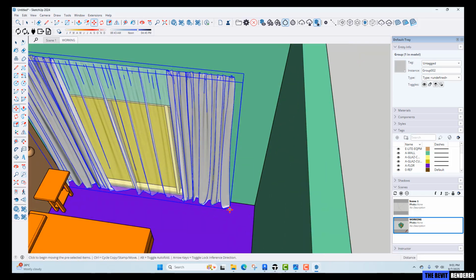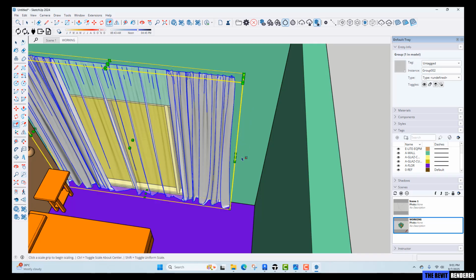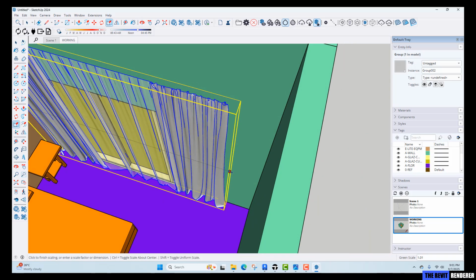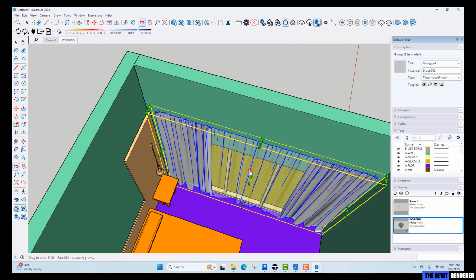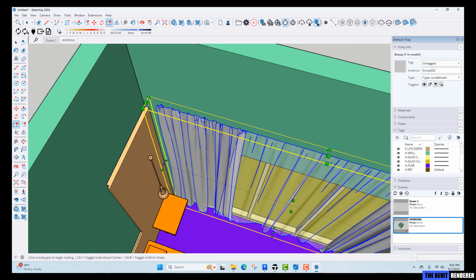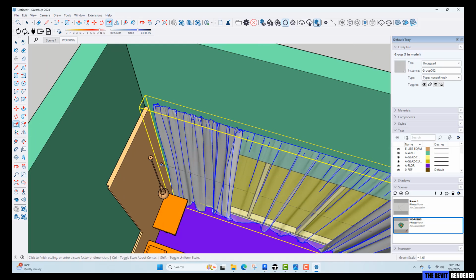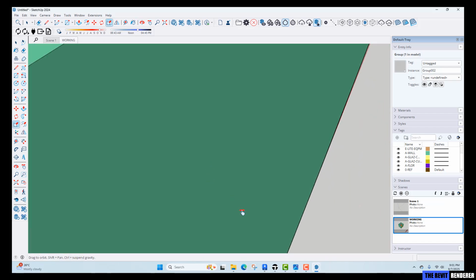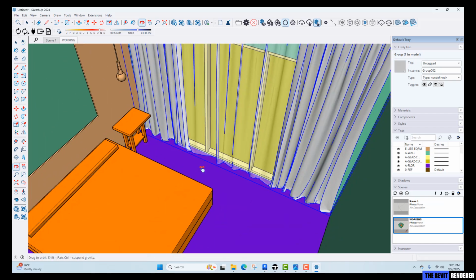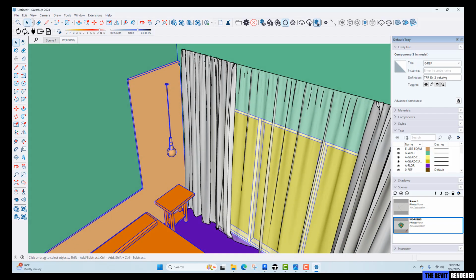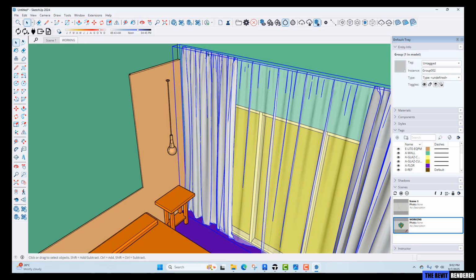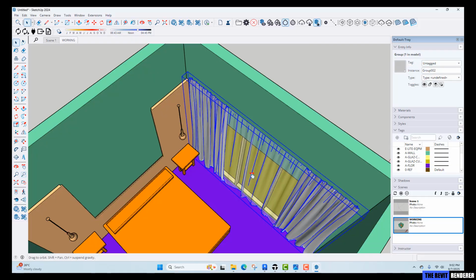So let me try to stretch it using the scale command S here in SketchUp. And then also this way. Then the height, I want it to go all the way up to 2850 mm, which is somewhere around the top of this built-up wall, which is actually good enough because this one will be hidden by our cove ceiling. So this one is good enough.